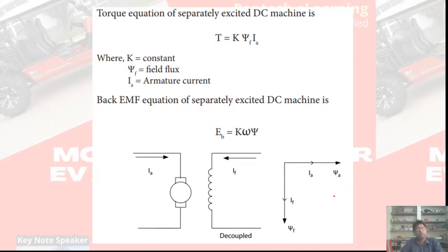When I need higher torque, I have to bring down the wheel RPM. So we'll apply clutch and change the gear, and vice versa, and so on. But in electrical machine, for the entire operating range, you can apply the maximum torque for all the RPM. How is it? That concept came from the separately excited DC machine.